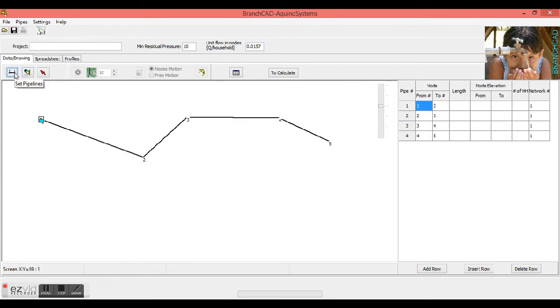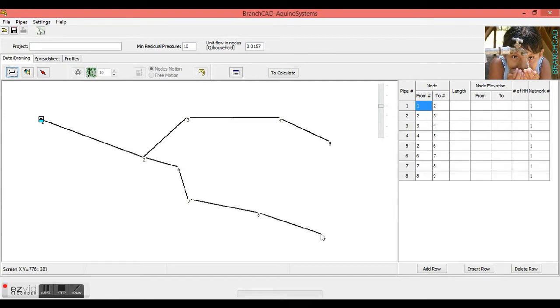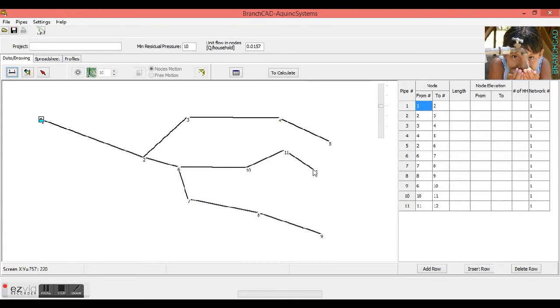Branches tapped to any node can also be drawn just by clicking on a point close to the node to tap, and automatically a section will be drawn. Continue drawing sections until the branch is closed by double-clicking again. Using this procedure, we can add as many branches as needed for our project. This is only a demonstration of how to do the data entry through a scheme.